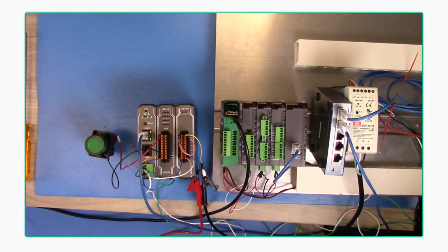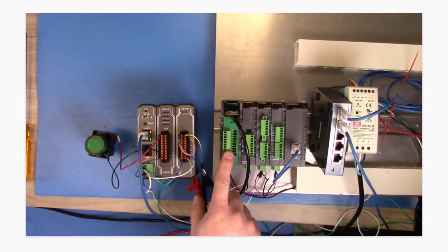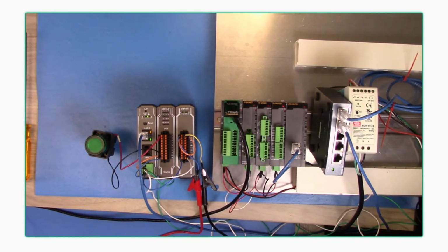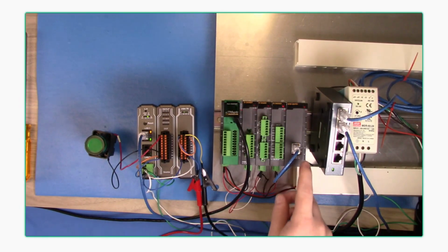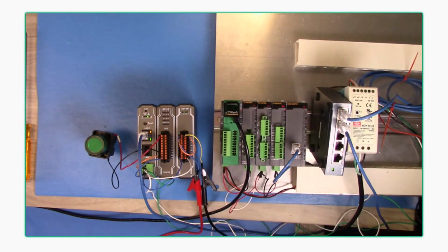By default, these CPUs can communicate via Modbus only as a slave over Ethernet. So they don't have the ability to act as a master on their own. So you do need the addition of one of these MODSENT01s. You'll see that in some other PLC brands as well, where you need kind of an expansion to give that master functionality. So in this case, that's what we're using.